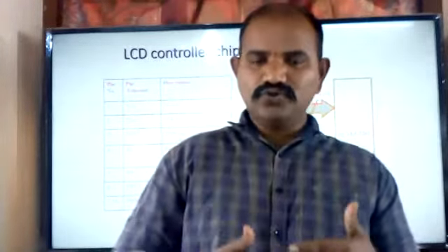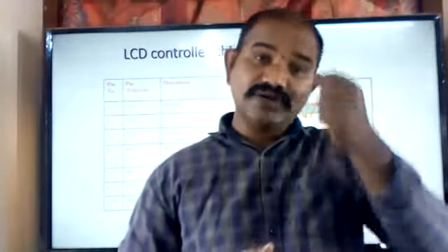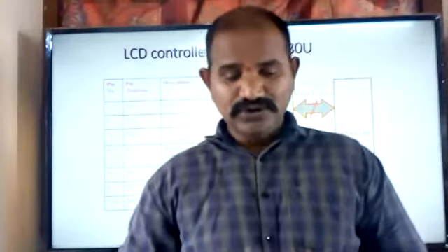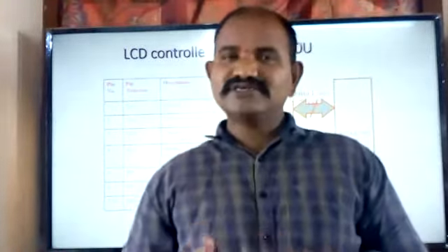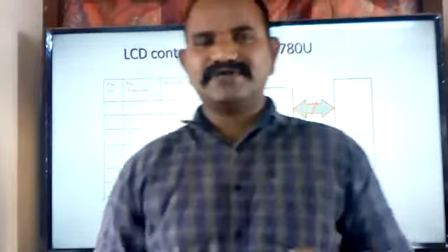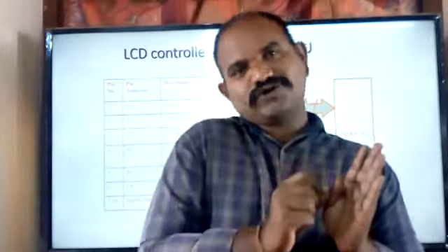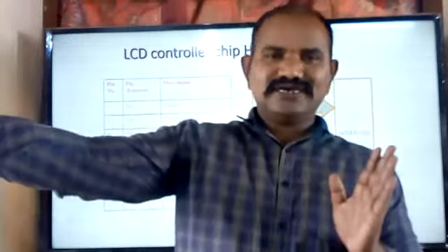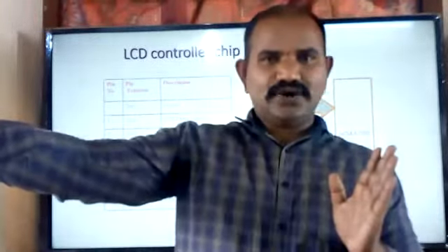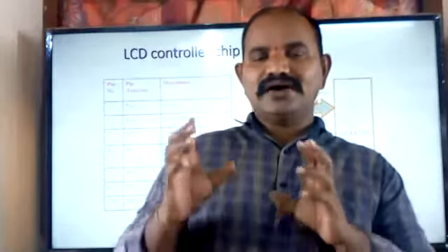The main intention of the command format is that there are rules and regulations. Let us suppose I have the 16 by 2 LCD module. When you would like to print information on the screen, you are going to take some decisions. Most people expect that the information should start from the left side of the display and keep on writing towards the right side, just like human beings writing on paper. How you would like to print the information on the screen, all those conditions are available in terms of commands.